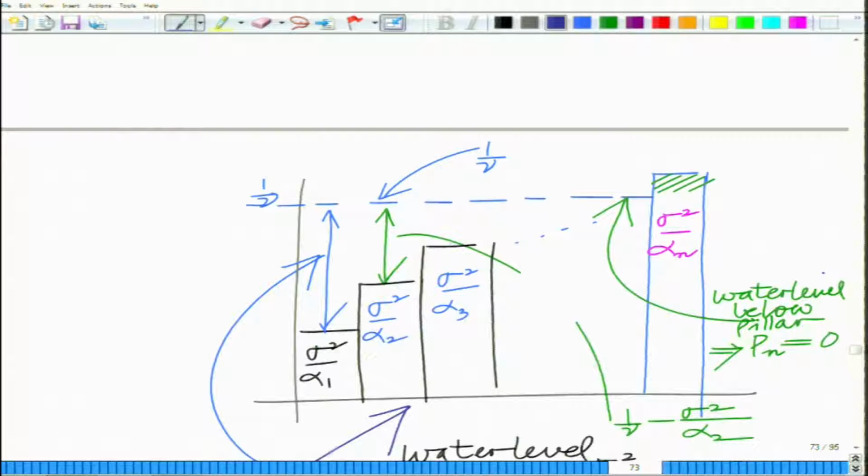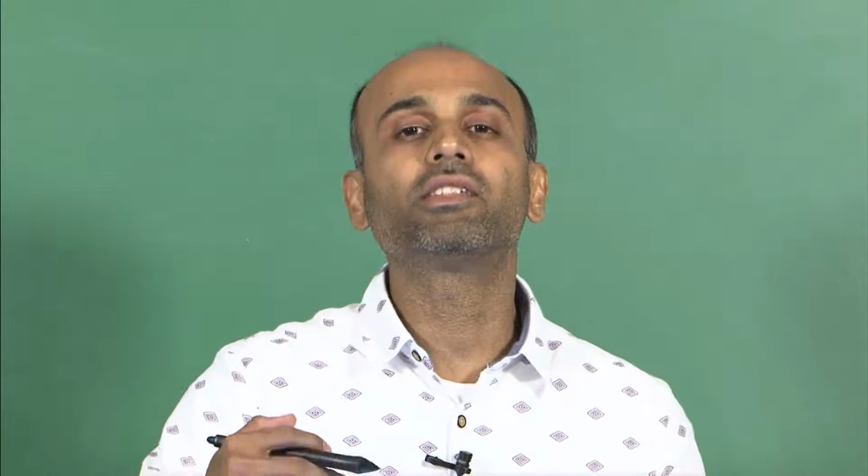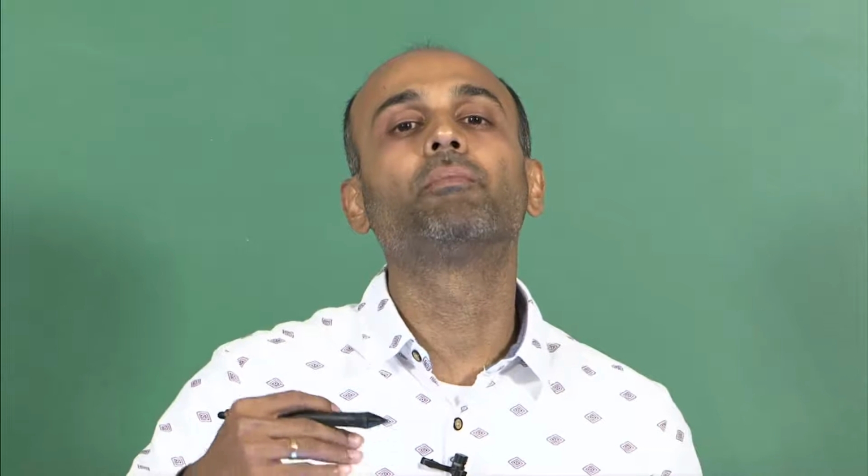Now, what we want to do is come up with a framework for optimal power allocation. Remember, we have seen the optimal power allocation problem: we have a total transmit power P, and a set of parallel channels each given by gain alpha I, and we want to allocate the power optimally amongst these parallel channels so as to maximize the total bit rate, that is the sum rate of this wireless channel.